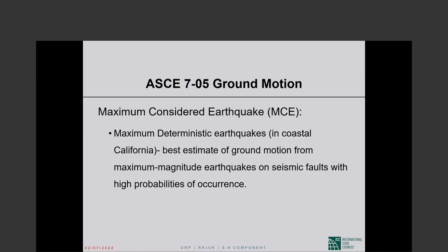Okay? Since these seismologists know the seismic sources, the maximum considered earthquake is the largest earthquake that can be delivered by the known seismic sources. This is also called the deterministic earthquake. In Bangladesh, you don't have to deal with a deterministic earthquake because you don't have those seismic sources capable of delivering large ground motion.